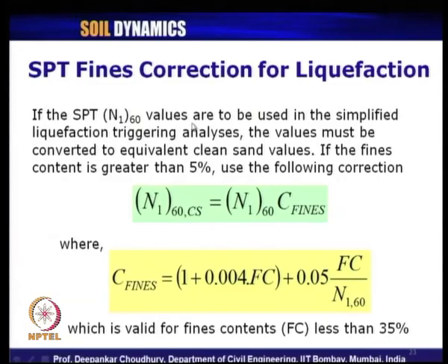Now, these values are to be used in the simplified procedure of liquefaction triggering analysis. Now, the values must be converted to equivalent clean sand condition. So, if the percent fines content in your soil sample is greater than 5%, then the following equation or correction factor has to be used. So, what does it mean?